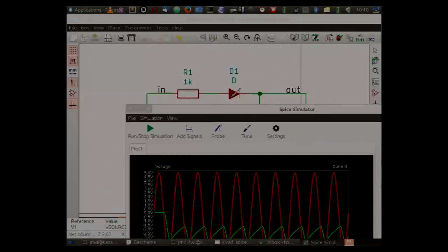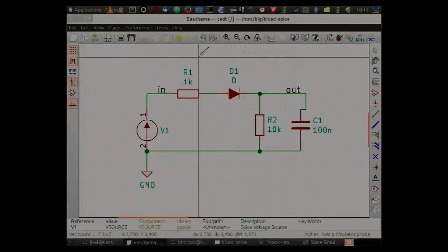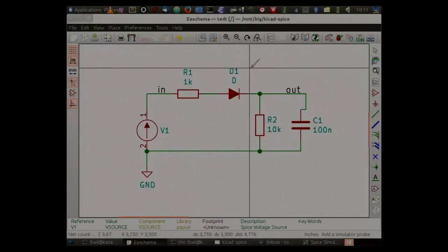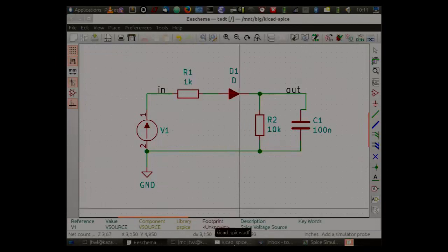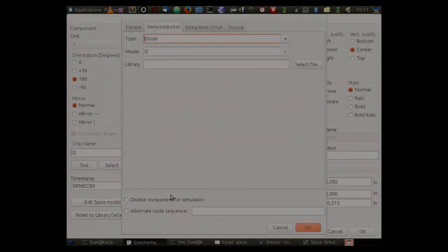But the ugly thing is that I connected the diode with this polarity, but there is something wrong. The plot is upside down, right? It's in the negative half. So, you know, there was a common problem with KiCad libraries when the transition was done between one version of the library and the other. And this changed the node mapping.